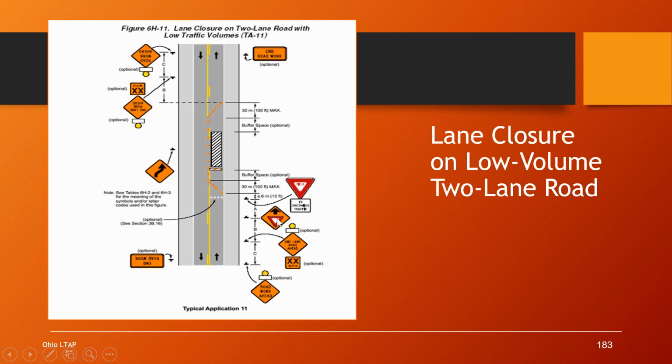And this is a situation where maybe some of you that work at the county or a township are chuckling because you're like, "Oh, we're never going to put all those signs out." Well, I'm not talking about a short, 15, 20, half hour type of job. We're talking about a job that might last all day, definitely more than an hour. It's then that you want to think about using these signs. If you're only going to be out there for a short period of time, then you might want to just stick with the flaggers.